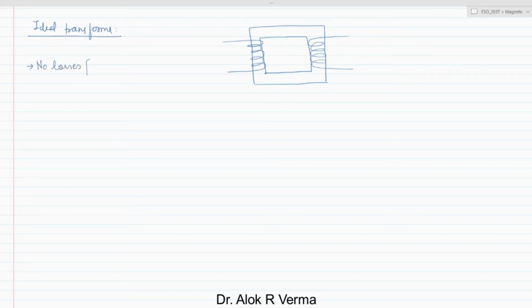With this, let us go into electrical or magnetic circuits. Here you have seen the coupled coil case, where we took the polarity of the dot and both currents entering. But in the case of a transformer, we assume I2 prime is the current leaving. So do not get confused. The second is no leakage flux, and no core losses.